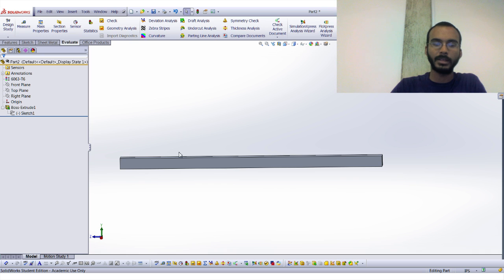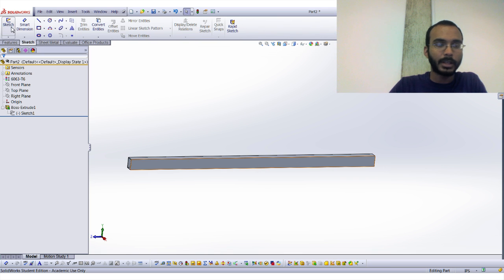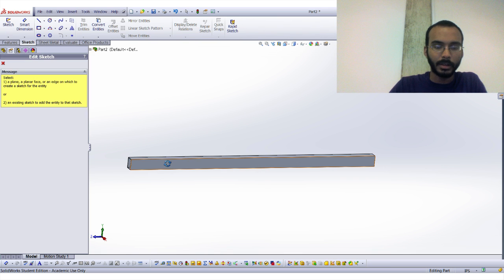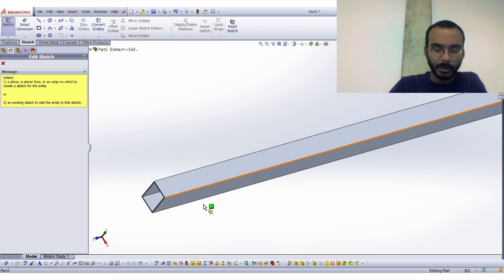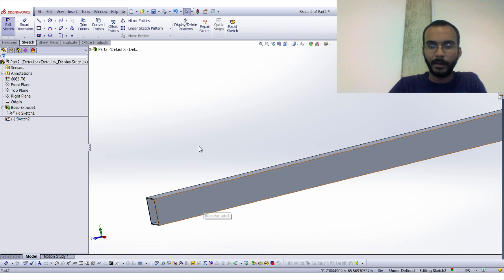To do that, you have to add sketches. There's a couple different ways to do that. You can right-click and click on the sketch button there. You can also go up to sketch here, click on the sketch button there, and then click the face you want to make a sketch. So if you want to click on the side or something like that, now we have basically the same sketch interface we had before, except now we're actually doing it on the side of the part.